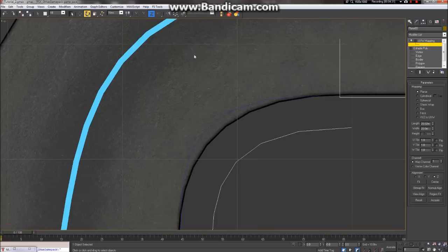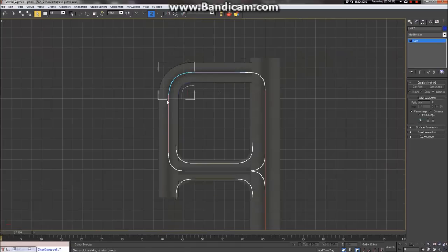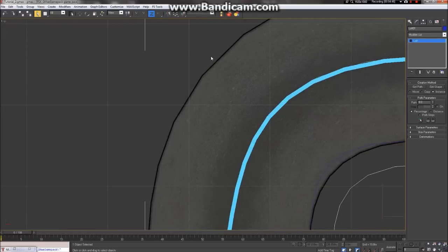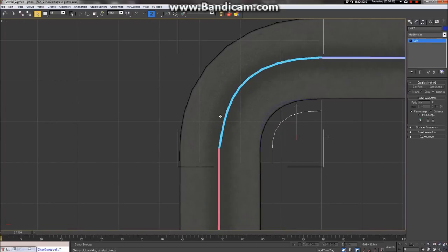Now we need to work on these lofts. And this is something a little different we have to do here. So we know that the texture should repeat about every 20 meters. So we need to somehow figure this out, because at the moment it's stretched along the length of the loft, I believe. So you can see it should probably repeat maybe once. Let's see, 1, 2, maybe 2.5 at most.